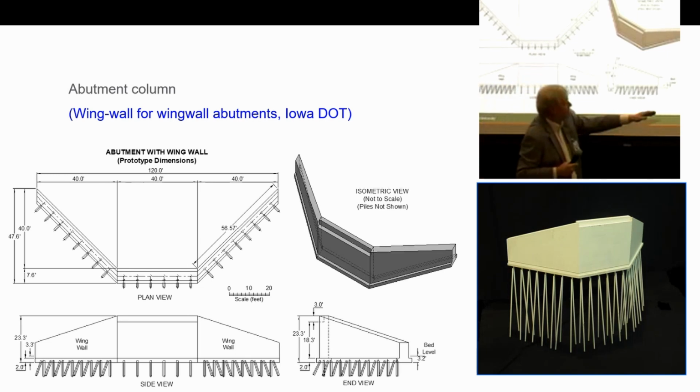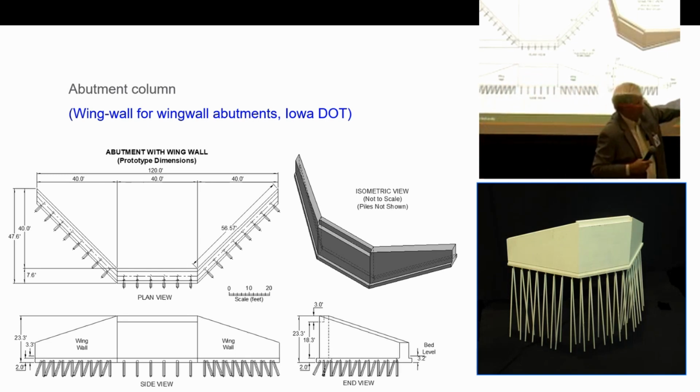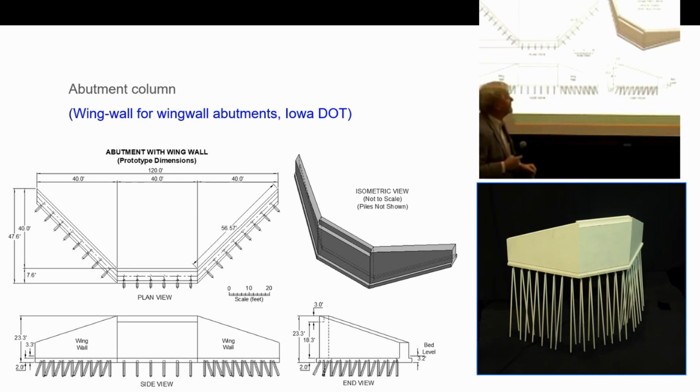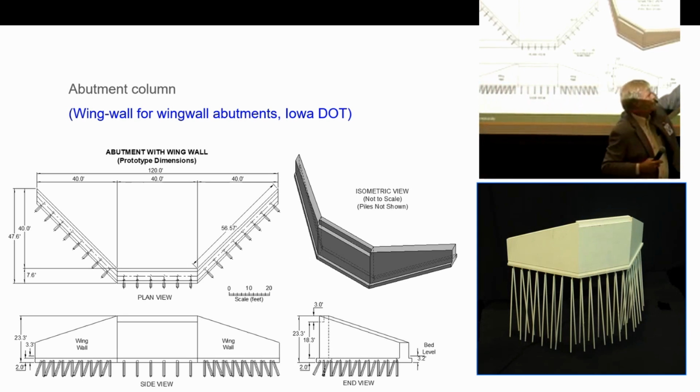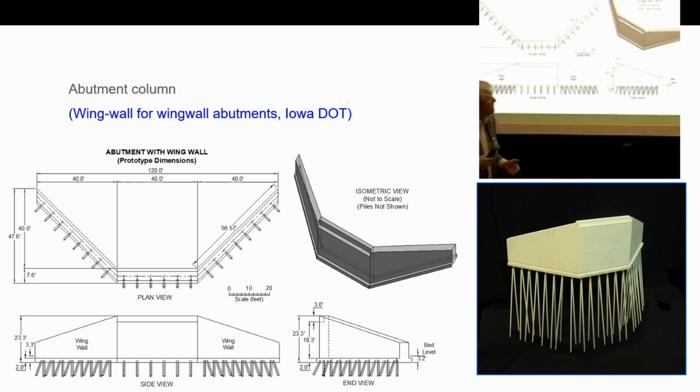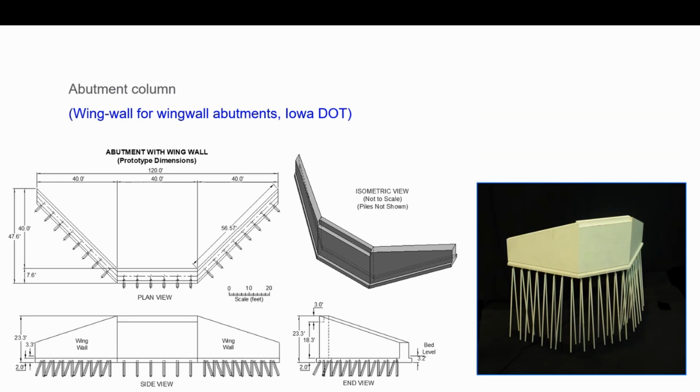And this photograph here shows you what it looks like at model scale. Again, the bridge sits in the notch up top there. And so your job as a hydraulic engineer is to figure out how high the bridge deck under lower stringer should be above the peak flow used for design, and how long the piles need to be to bear the weight of the bridge and the part of the bridge and the column there.